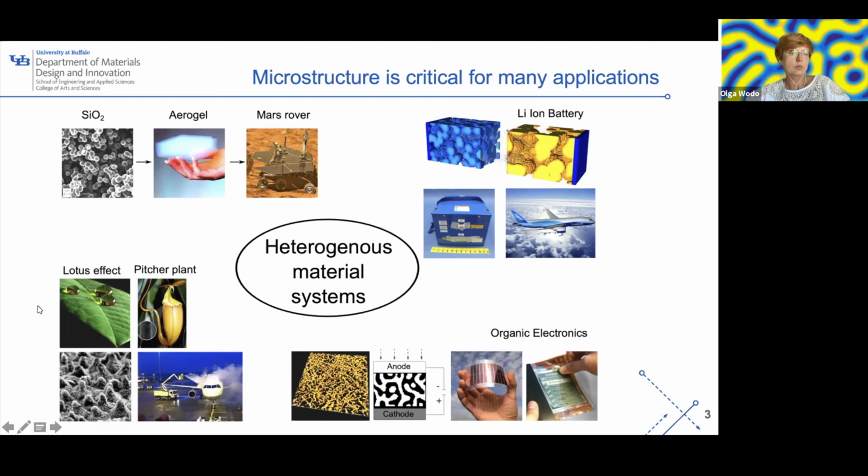Right? Looking closer to nature, when we look into the structure of the leaf, the surface of, let's say, a lotus leaf is interesting. When you zoom into the microstructure, you will see those pillars, right? And those pillars are interesting because when, let's say, a droplet of water lands on the surface, they provide the suspension, right? But additionally, if we zoom in, we'll see those pillars are additionally coated with a kind of wax, right? So that the water will not want to stick to those pillars. So again, by looking into microstructure, we try to understand what really controls the properties.